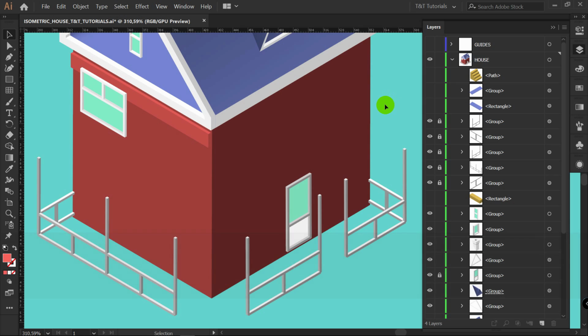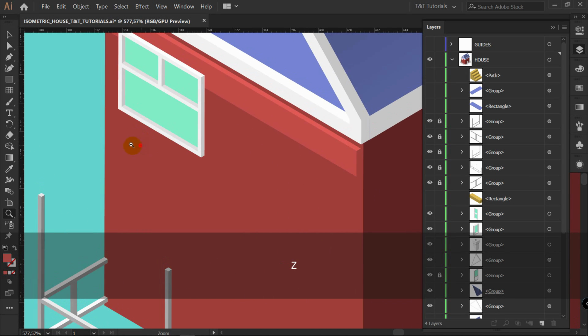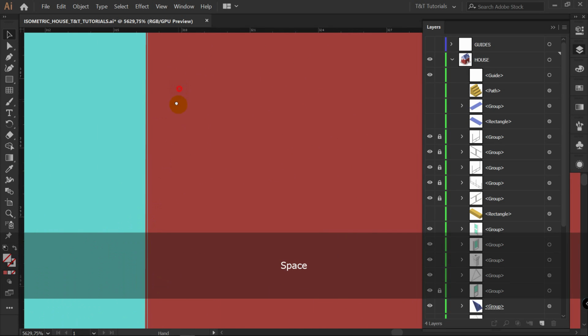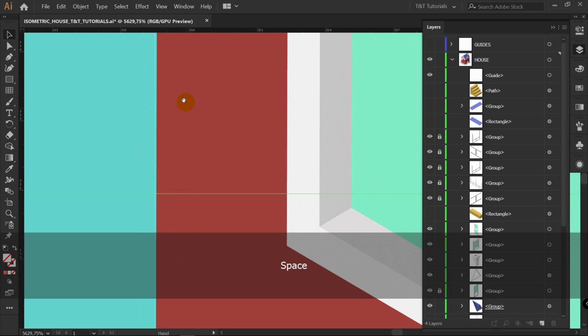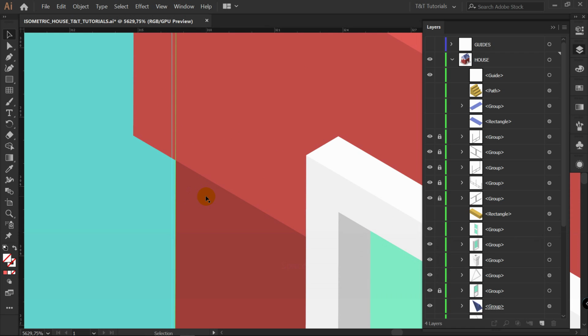And this is a very important part. Please pay attention if you want to make everything correctly and if you want to make your artwork look professional. What you should know about 3D effect is that it adds some distortion. If you drag a guide like so, snap it to this side, as we're moving to top, you can see that this object is not following the straight guide. This is not a big deal, but if you don't know this, you won't ever make good results. Your lines would not match and you will have big problems.